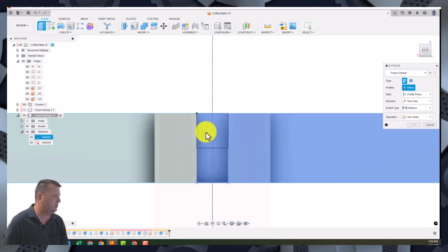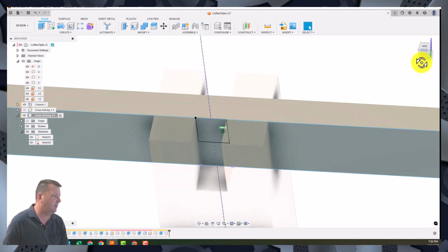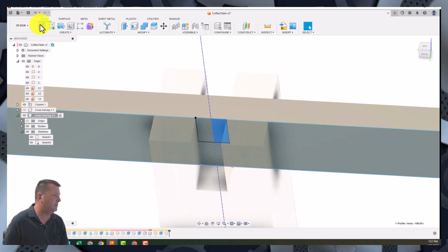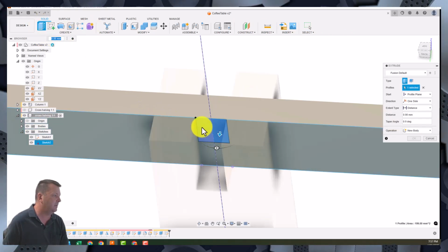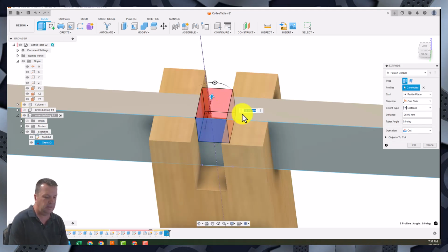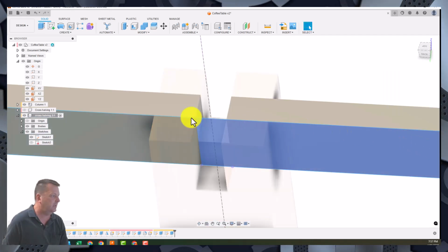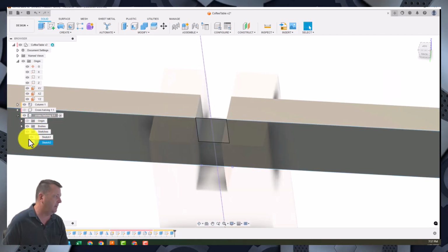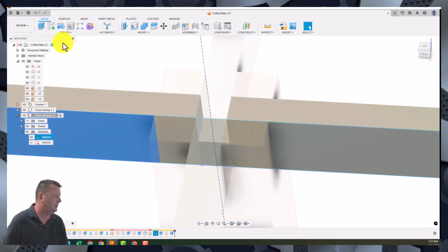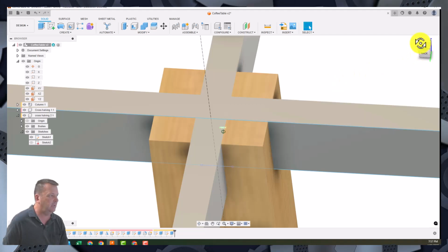We can go to extrude. Oops. Sometimes it does that. I'm not sure why. Grab that and extrude those two shapes to do both. There we go. And we can drag that through, or we're just going to type in -19 and go OK. Now that was the bottom. I think we did that the right way around. Let's have a look. Turn the other one back on. Go to the top level, and that looks pretty good to me.